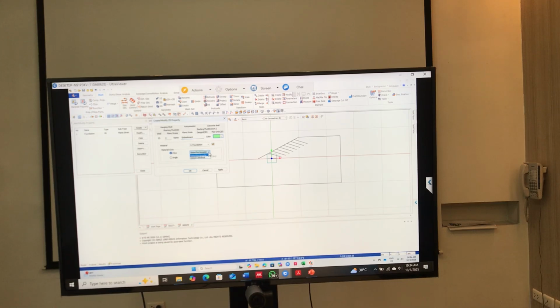You just don't touch on it now. After meshing, you can see that all the coordinate systems are going in the same direction. If the green arrow is facing up, the red one is facing this side. So when you finish meshing, you should make sure that all these coordinate systems are in the same direction.